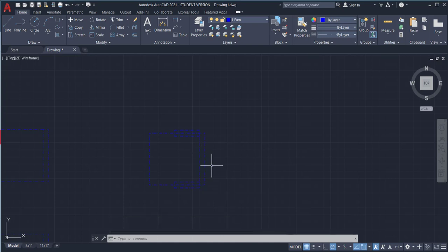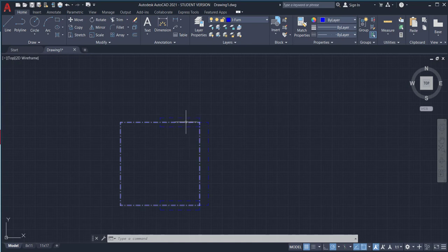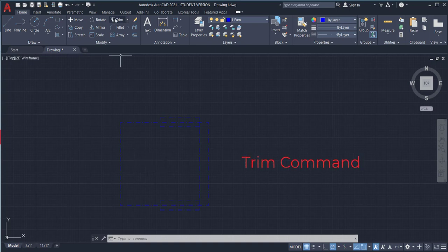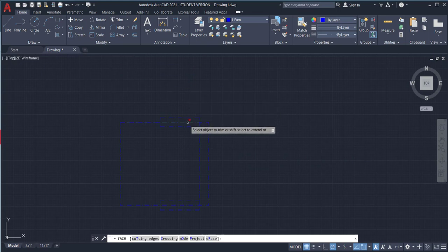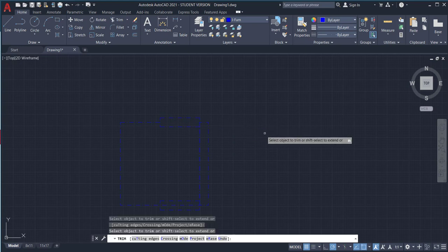The only problem that we have right now is that there's a line in the box, and we never show what's underneath things in AutoCAD plan view. So we do want to cut it out so that it looks like we're actually looking down on the chair. There's no X-ray vision, in other words. So trim, remember trim? Trim button. Select the object to trim. What's so great about trim nowadays is that you can just click on that thing that you want to trim. Remember, it has to be intersected in order to be trimmed.